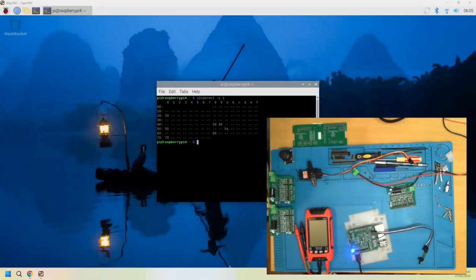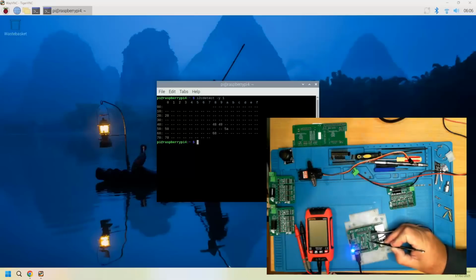My name is Ray, and in this video, part 13 of the Robo Hat series, I'm going to cover the ADS1115. The ADS1115 is a 4-channel 16-bit analog to digital converter, and on the Robo Hat I've got 2 of those installed. They are located here and here on the board. So 2 very small chips, and they're not that difficult to drive once you get the hang of it.